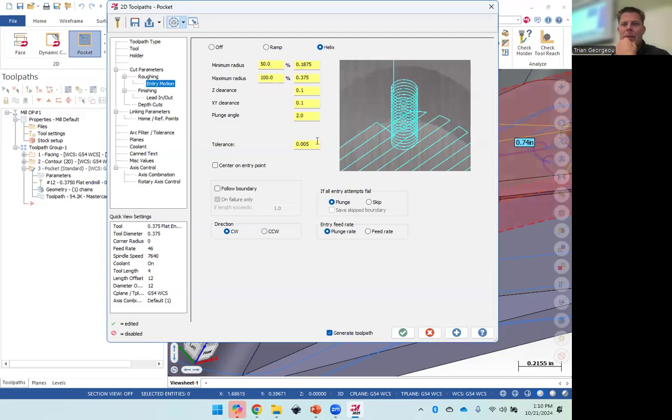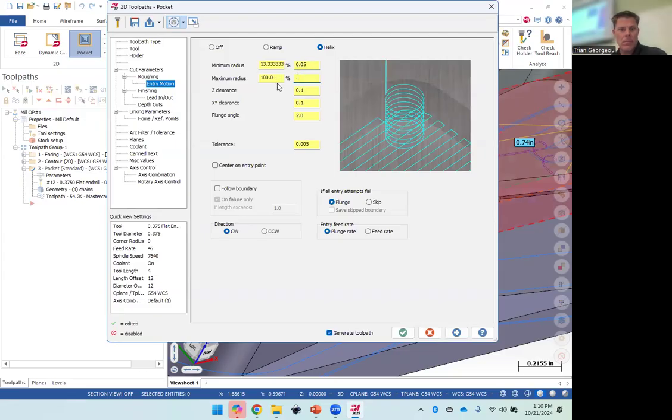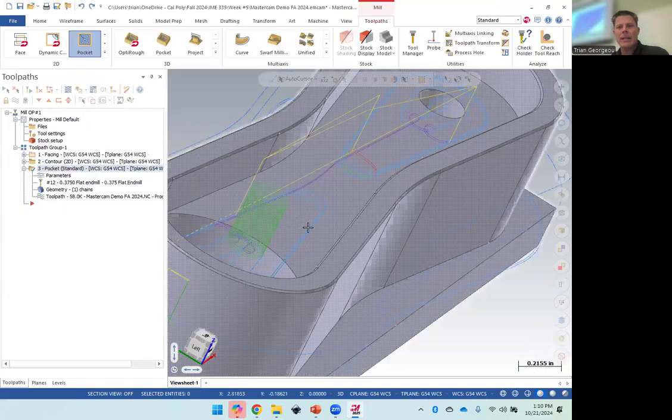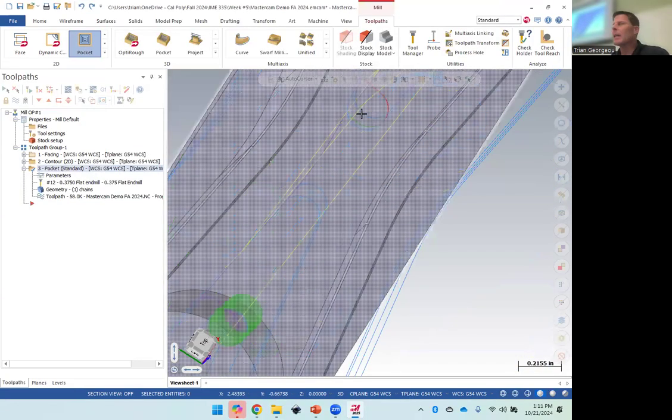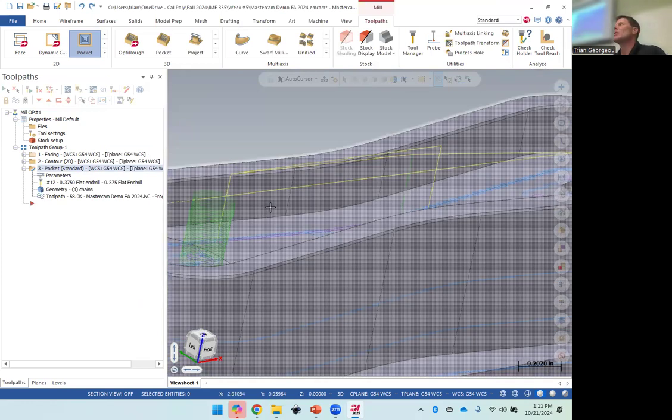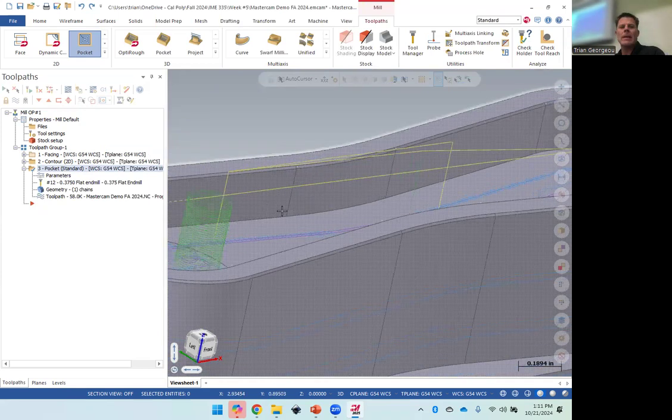So does everybody see how I didn't do a helix either? It's because it can't with the size of parameter that we gave it. So now it can do a helix down in, but do you see how it doesn't link in between? The cutter is just too big to do that. So let's switch it to a 1/4 inch. Sound good?